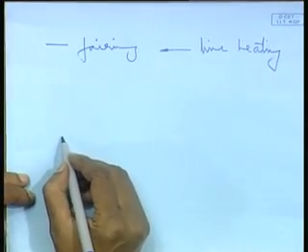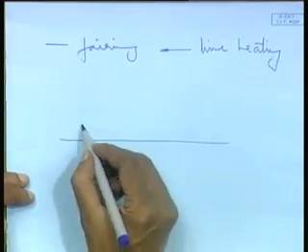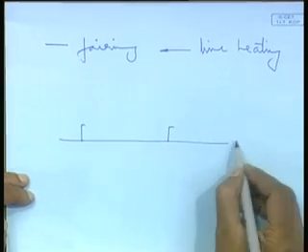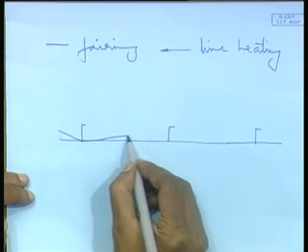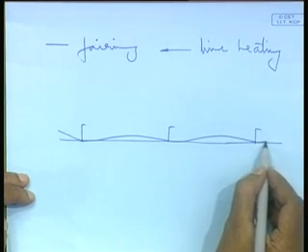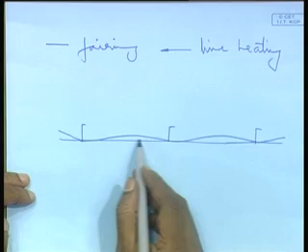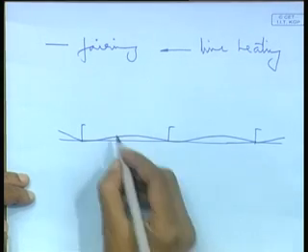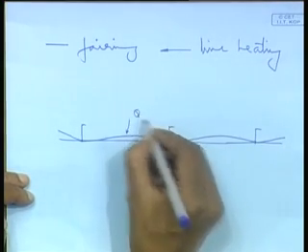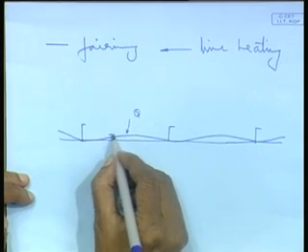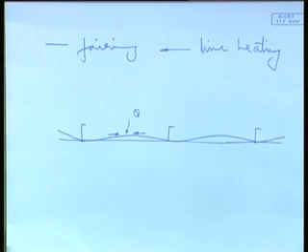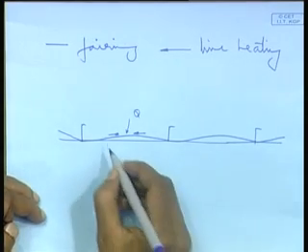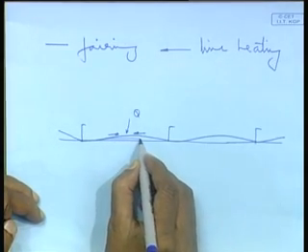The same thing works the other way: I apply it to a curved plate, I get a flat plate. That is also true. Like here, when this buckling deformation has taken place, suppose here angular distortion has taken place, here your buckling has taken place, right. So, how to reduce this buckled part? If I apply heat here, what will happen? Contractional forces, shrinkage forces will work, the plate will shrink. Once the plate shrinks, it will tend to flatten out.